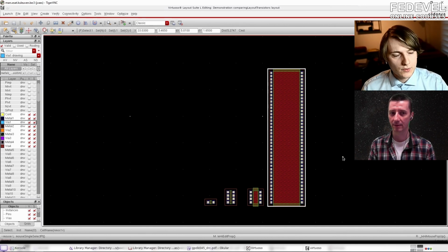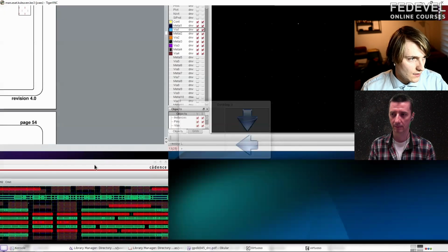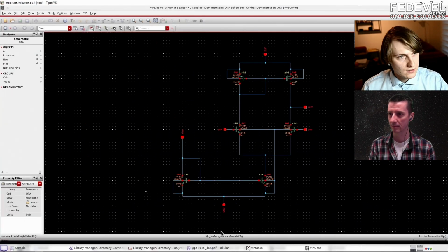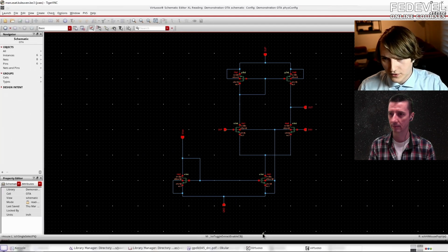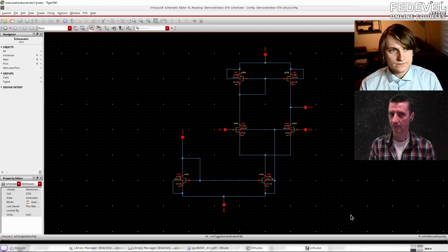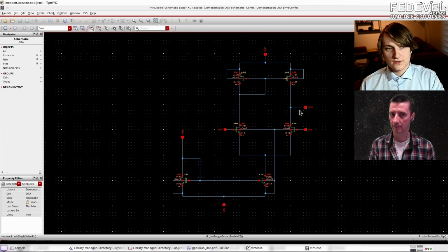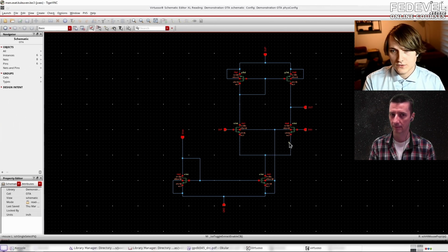Okay. Yes. So when you think about designing an analog cell, what you do is you play with output resistances, input resistances, the gain of a single transistor, and if you have multiple transistors in a cell, for example here in an op-amp, a very simple OTA, right? So you design this schematic, and every analog designer learns this; it is one of the first cells you see in IC design. It's a differential input pair with a current mirror load and a current mirror as a tail, right? So you design this schematic topology, and then if you do lower speed analog, you can really go into hand calculations and calculate, I want this gain. So then this device needs this output resistance, and this device needs this gm, what we call it, so voltage to current conversion.